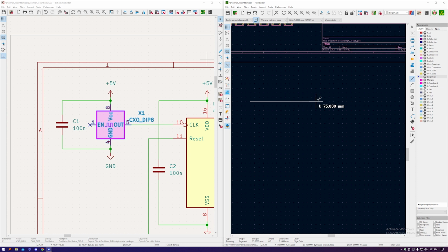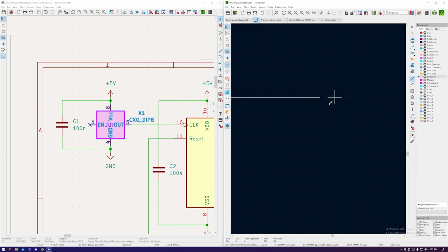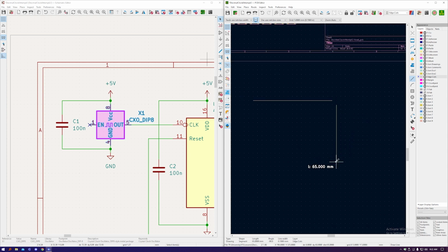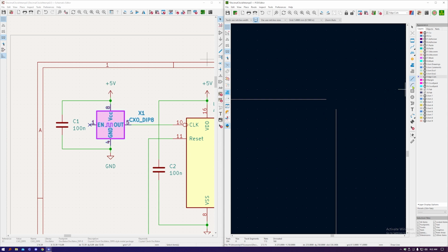So start with this and draw a line that's 90mm long, then cancel. Then if you can see the grid, hopefully it shows up in the video, go 1 dot right, 1 dot down, and now do a 90mm line down. And do the same thing, so you basically draw a square with missing corners. Then what you want to do is select the arc tool, and the arc tool will always draw clockwise. That's the most important thing to remember.